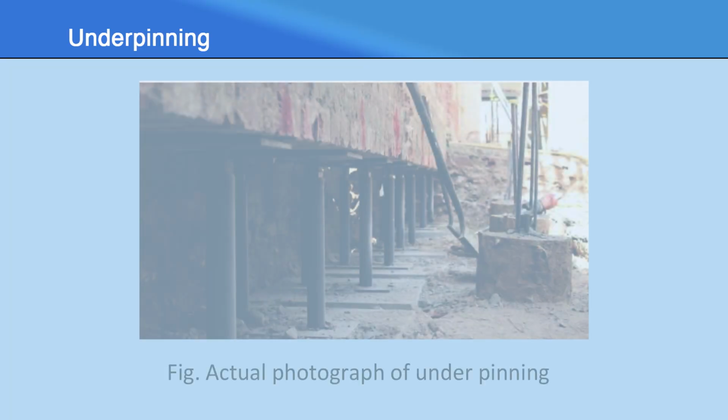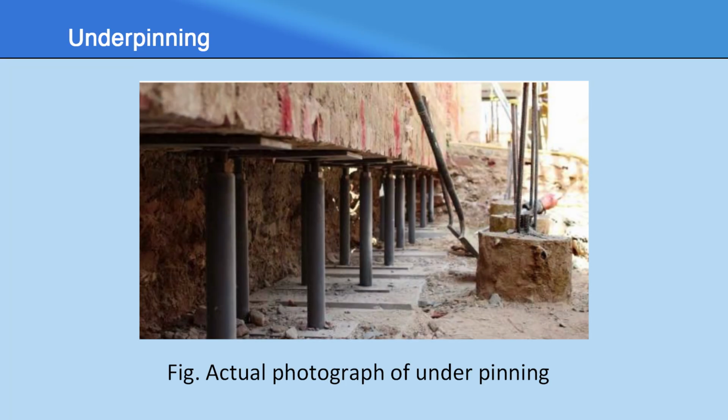to support the additional floors or loads, to repair foundation that have been damaged by external factors like subsidence, earthquake or a change in soil condition, to construct the basement in the existing building. Application: building expansion, renovation, structure repairs and in the area with poor soil condition. This is the actual photograph of underpinning, in which you can see the foundation is raised, or you can use it for the strengthening of existing foundations. So, underpinning is basically used to raise the foundation.